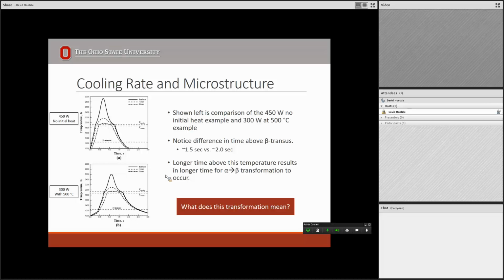Understand that. Basically, equilibrium states: if you hold it at a certain temperature for a long time, it creates a certain microstructure. But if you cool it really fast, you can freeze in a certain microstructure. If you were to hold it for that period of time, it's actually going to freeze a shape, and you're not going to have a microstructure. So the time at which you hold a material at a certain temperature is important.